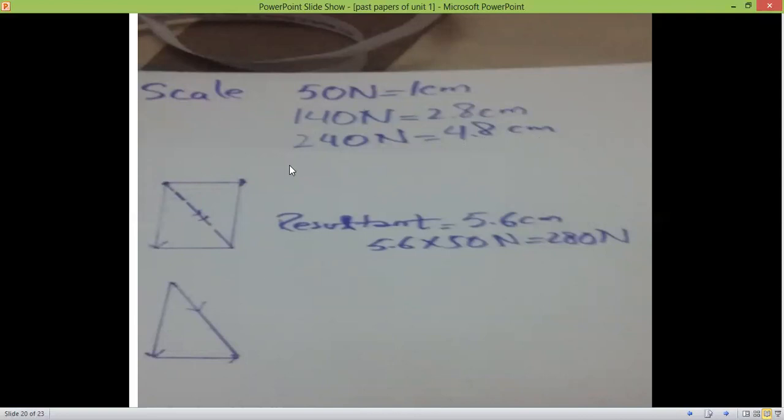So we can find the resultant either by parallelogram method or head to tail rule method. According to the parallelogram method, these two forces should be such that their tails are coinciding. So one force is the weight acting in the downward direction, other is the tension acting in the horizontal direction, and the parallelogram is completed. How to get the resultant vector? Starting point is joined with the opposite corner.